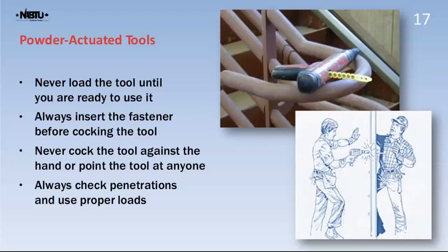It's all about training, and don't just be the guy who says, "Yeah, give it to me, I'll figure it out." You want to have somebody show you how to use this. You always want to insert the fastener before cocking the tool. You never want to cock the tool against your hand or point the tool at anybody. Again, it's just like a gun.